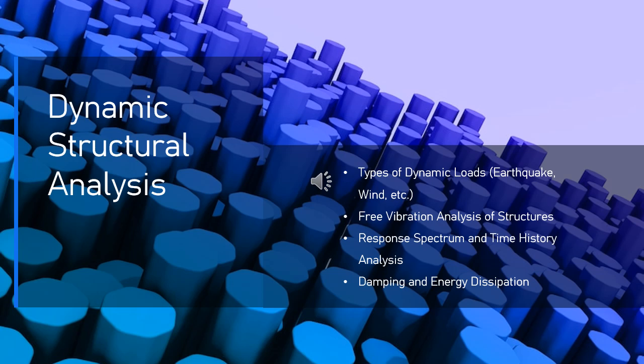9.2. Damping models in structural analysis. In dynamic structural analysis, damping is typically modeled in one of the following ways. Viscous damping model. Equation. The viscous damping force is often modeled as Fd equals c x-dot, where Fd is the damping force, c is the damping coefficient, a constant that depends on the material and structure, and x-dot is the velocity of the structure.